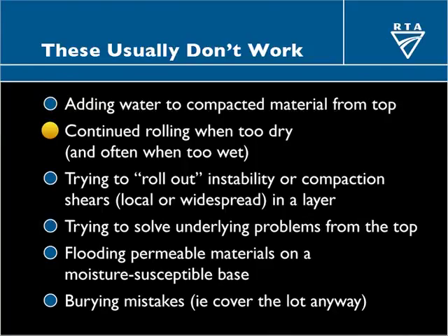Just keep going with the rolling when it's obviously too dry, and sometimes people do it when it's obviously too wet. It generally won't work. We've seen why. As you get away from optimum moisture content, it just gets harder and harder. If you do continue rolling when it's too dry, particularly, you'll find yourself way out on the right-hand side of that diminishing returns curve that we looked at earlier. Much effort, very little return.